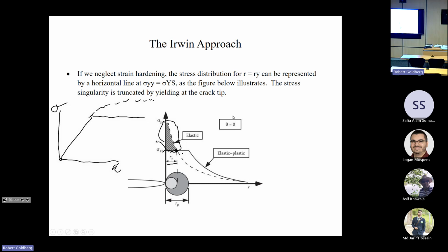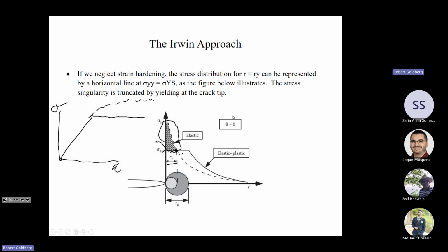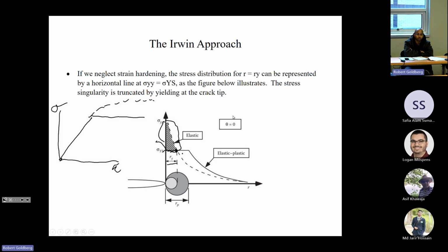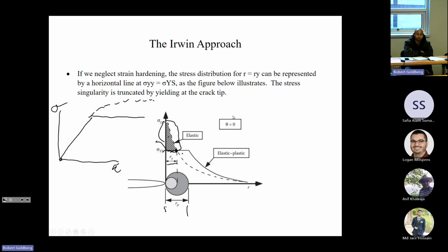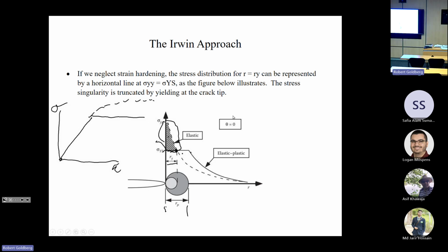They have to be redistributed within our stress displacement curve. We have to redistribute the stresses within the rest of this zone. So we have to say that the plastic zone size is actually bigger, because we have to take those stresses and redistribute them so that if we do an area under the curve, we get the same results. We account for their effects by expanding this plastic zone size.